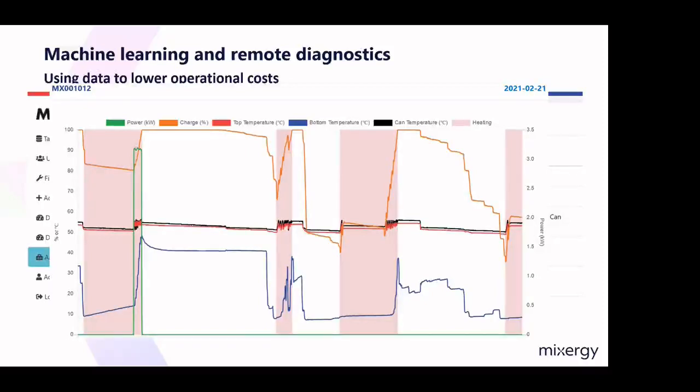If that's been enabled, the machine learning is then able to identify if the actual heat source has a problem. So if the boiler is still cycling after that method has been employed, it shows it could be a problem with the heat source, whether a partial blockage in the main heat exchanger, an NTC temperature fault, or a weak pump. But it's able to report back to the asset manager or homeowner to say we've got an energy efficiency problem with the heat source.